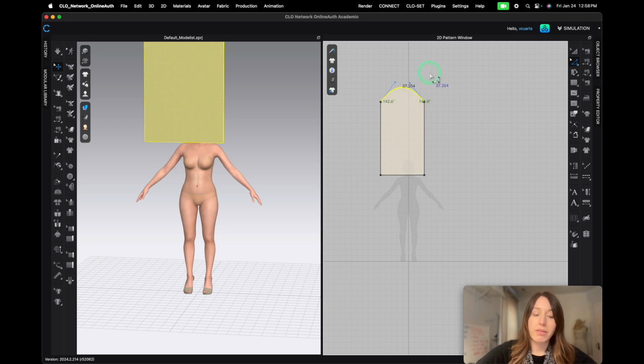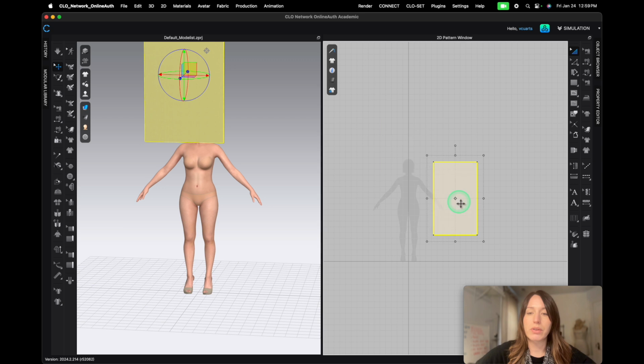So that's a very handy alternative tool to know, holding Alt or Option while you're in the Z edit pattern tool. So start to use those hotkeys. It's very, very useful.